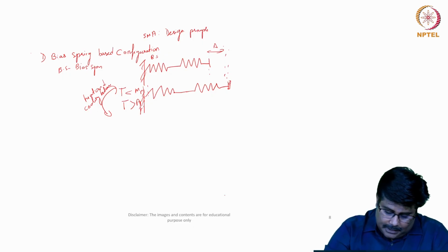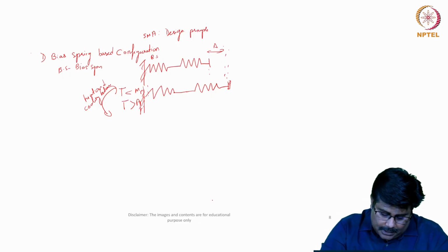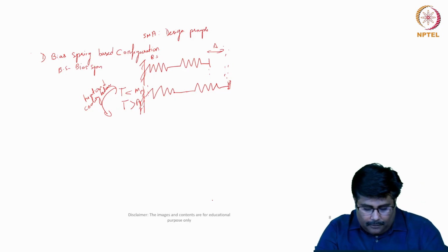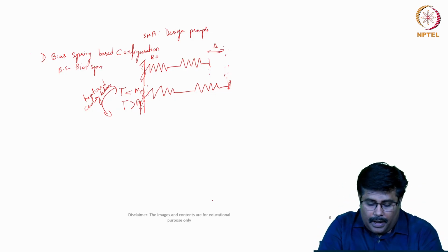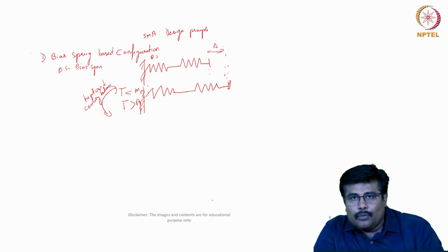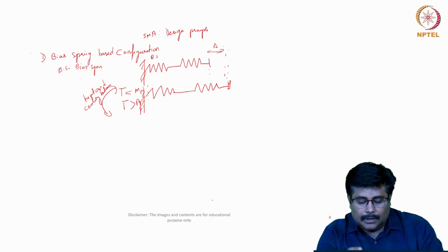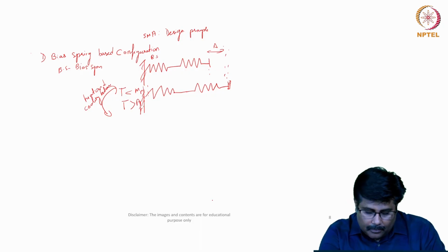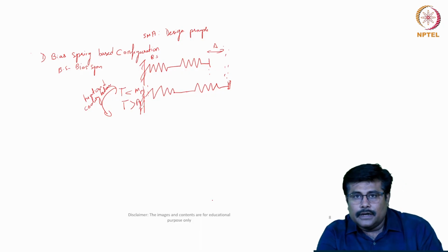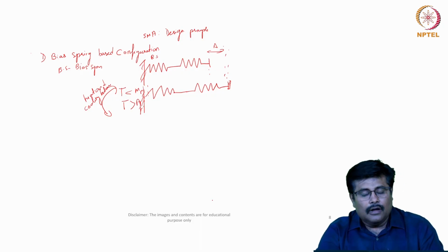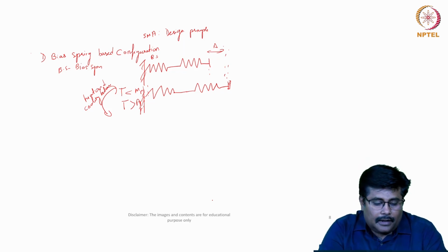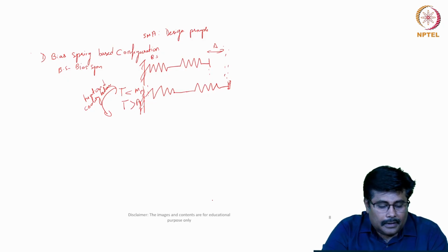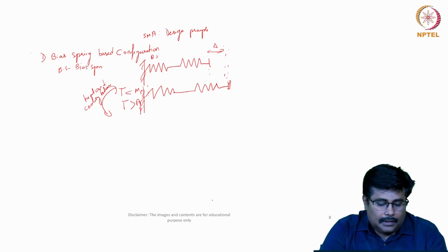Now, as far as this particular case is concerned, the system consists of a bias spring and the SMA, which is pre-strained by a deformation delta attached at both ends, so that the system remains in a deformed state after mounting, and this deformation induces a reorientation of martensite variants. The equilibrium point is found by looking for an equilibrium between the force applied by the SMA and the force resulting from the bias spring action.